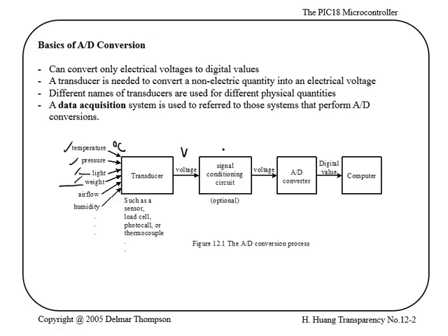And then you have a signal conditioning. So that signal conditioning is the one that maps the Vmax to Vmin to your VDD and ground value to feed to your PIC microcontroller. And if you want, you can skip this process and tell PIC directly that this is my Vmax, this is my Vmin, condition yourself. But that has its own costs, and we'll talk about them later. And then the AD converter is going to go through an iterative process of converting that analog voltage into a digital value and then use that digital value in your computation.